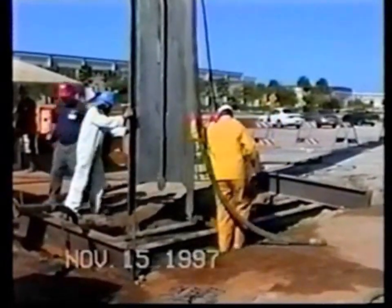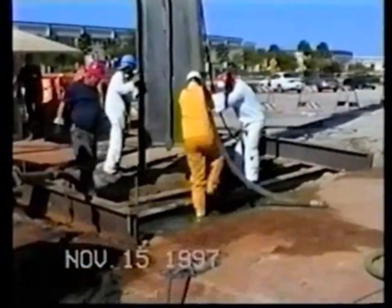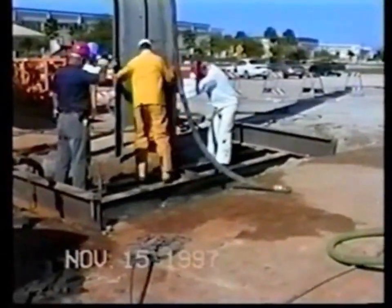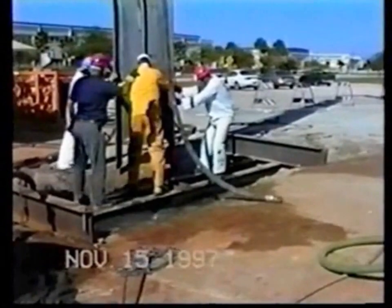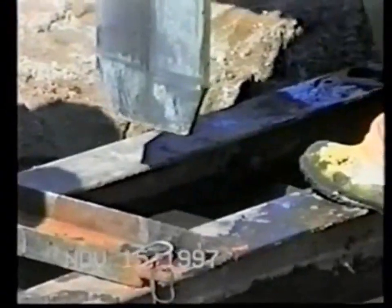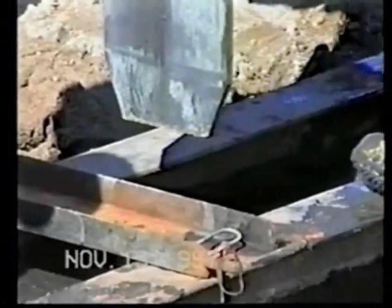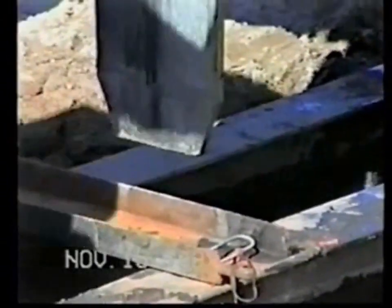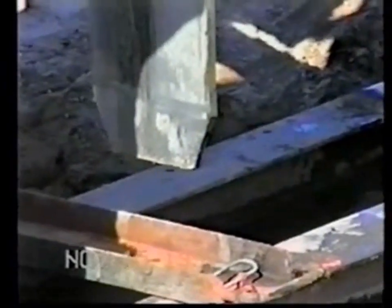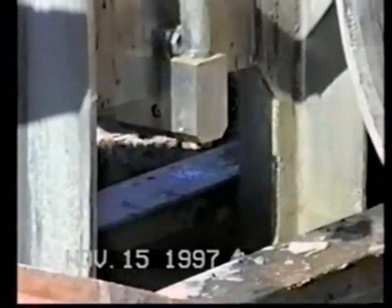This process utilizes a guide beam that supports an injection nozzle. The nozzle houses high and low pressure ports used to cut the formation and fill the void with an iron slurry. The beam used in this process is a 36-inch I-beam with the corners cut from the leading edges of the flange to facilitate positioning in the guide box. A movable lateral plate provides control of the positioning during emplacement.